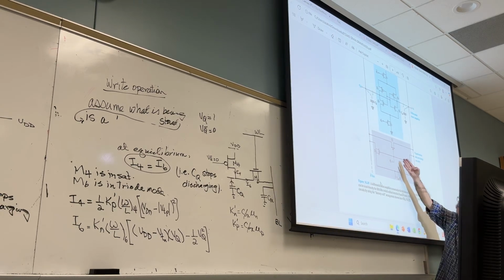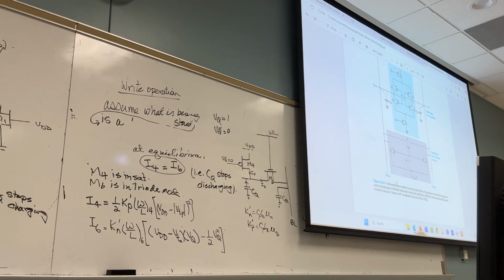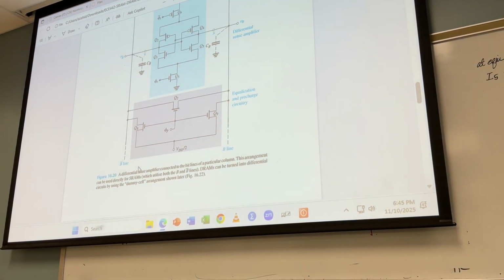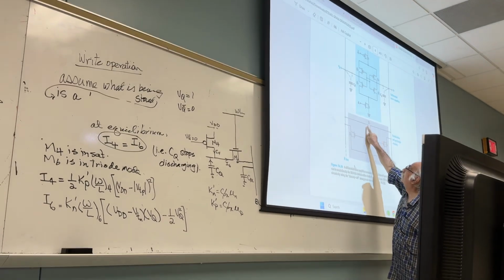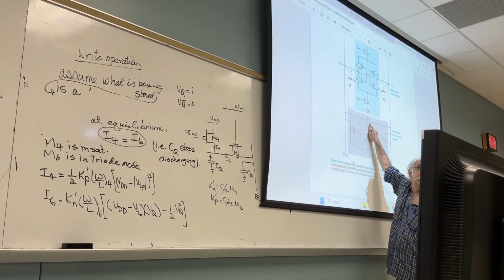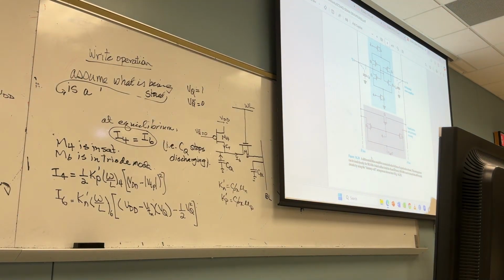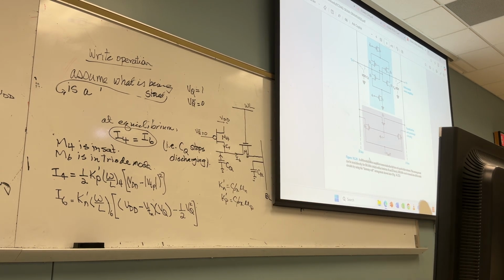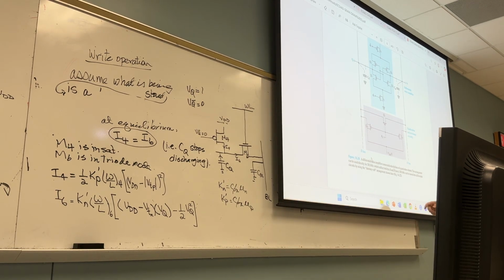But can you tell me what is the function of Q7? Level them out. That makes sure that both of them are VDD over 2. Do you follow me or not? The balancing. He needs to make sure that this voltage, because when this one is on, what does it behave as? Short. Yes? This voltage and this voltage are the same. What does he call it? Equalization. Did you get it? Okay. What remains is the middle part.